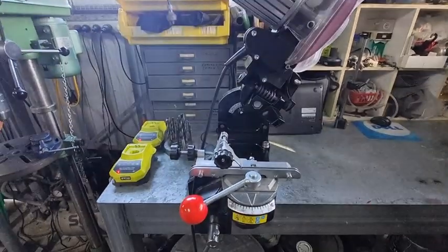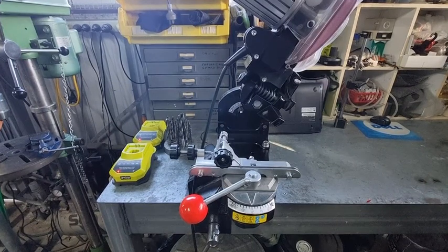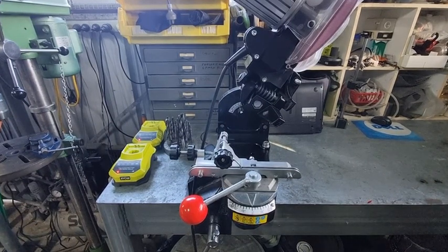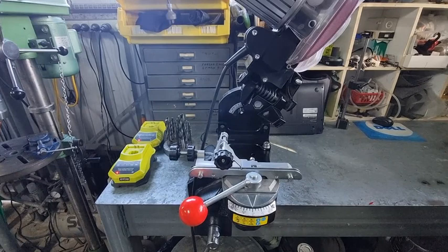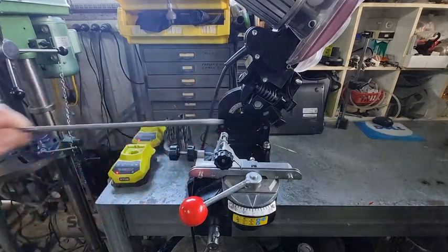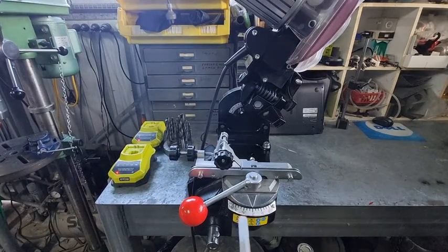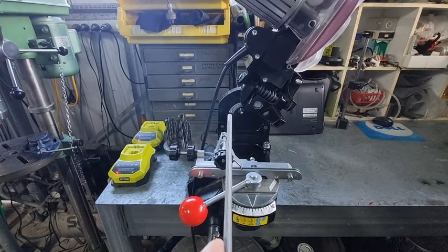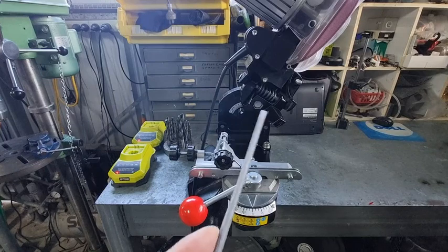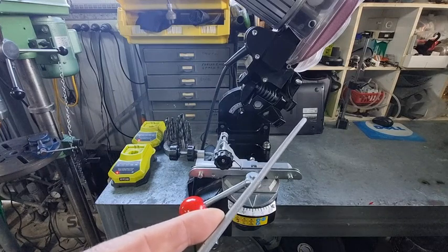Well, what you've got to realise is that you've got to go back before angle grinders, or chainsaw grinders, I should say, were invented. So what they used to do back in the day when they had files to sharpen up your chainsaw before the grinders came along, they would tell you to hold the file. So if your chainsaw bar was running this way, they would tell you to hold the file perpendicular, which is 90 degrees, move 30 degrees and proceed to file. So that was your 30-degree filing angle.